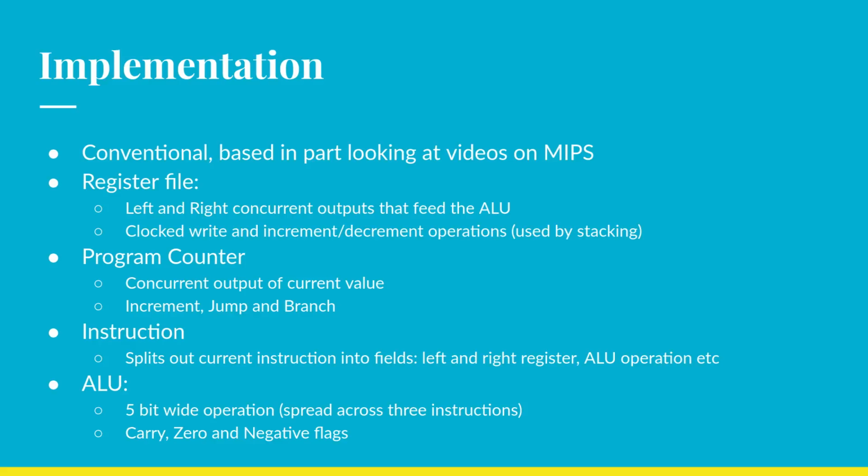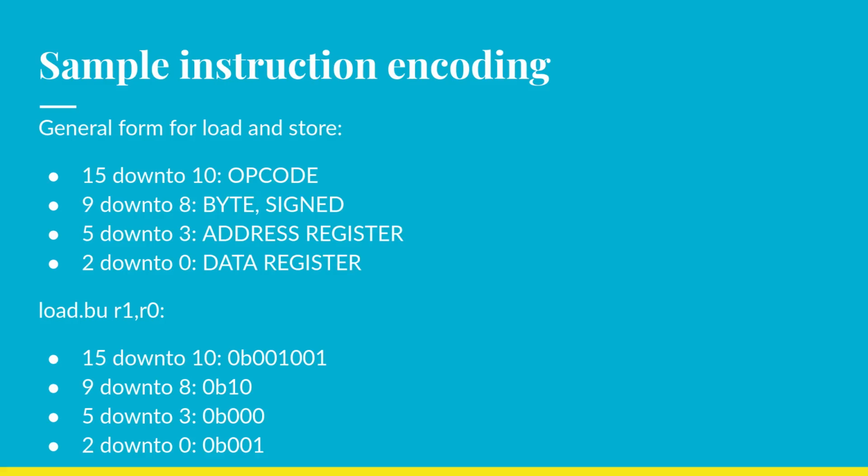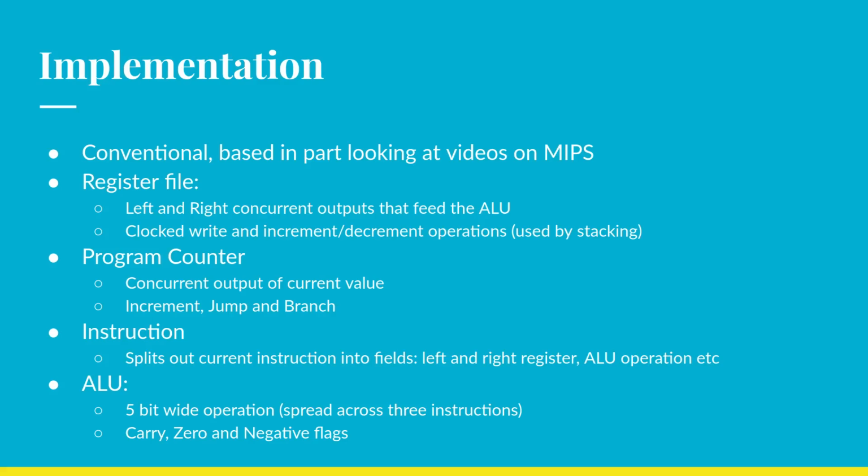There's a program counter which can do the branch calculation itself, so it doesn't use the ALU. There's an instruction register that holds the current running instruction, and feeds out back to various places the various fields as shown there, and other ones into the places that need it.